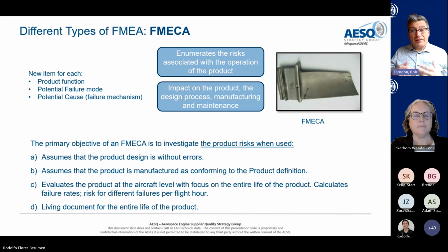And again, because it is concerned with safety of the product in operation, the FMECA should live throughout the life cycle of the product in operation. Okay. And it should be a very thorough analysis. It should look at every function and every potential failure mode and every potential cause of those failure modes in order to evaluate the overall safety level of the product that we're looking at.